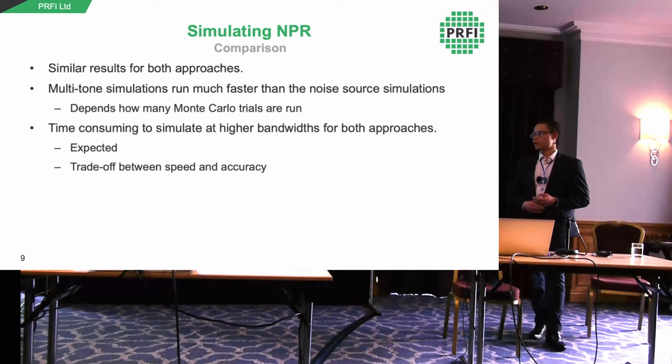The multi-tone simulations ran considerably faster than the envelope noise simulations, by a factor of about 8 to 10 times. So the multi-tone simulations might take 2 or 3 hours to run, but the envelope simulations we were having to run overnight. So it wasn't quite as practical to do those. Though that does depend on how many Monte Carlo trials you run. If you need to run more, that gap closes.